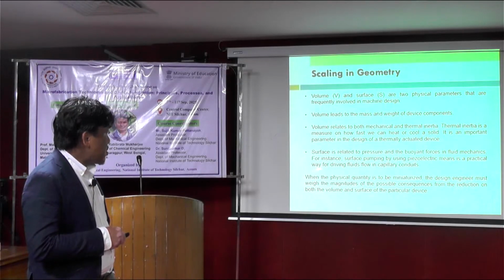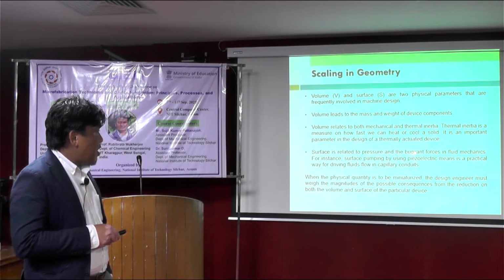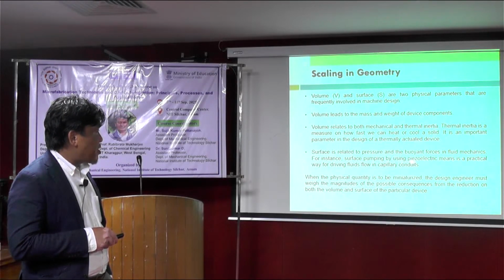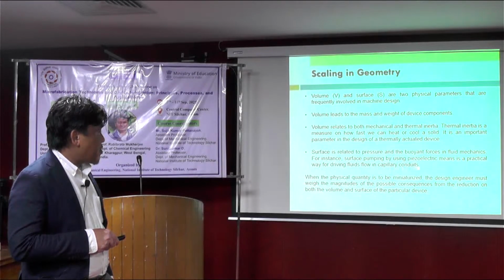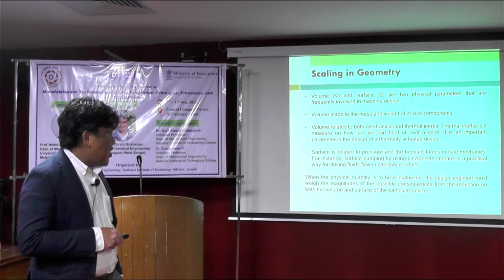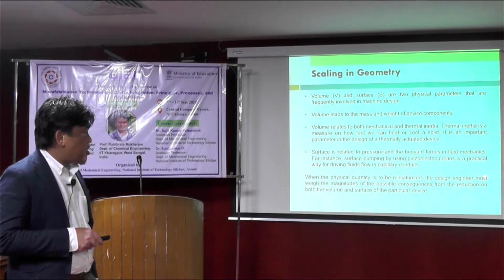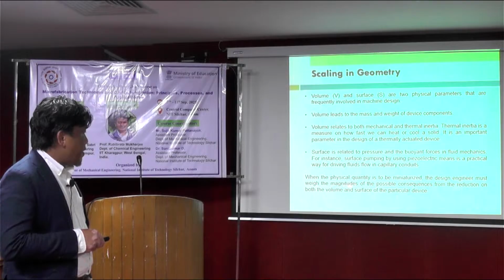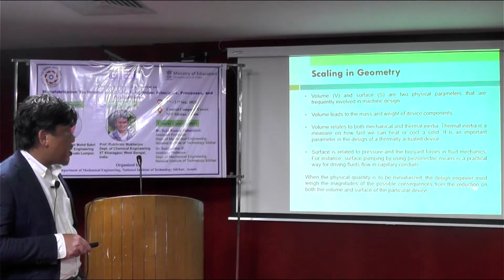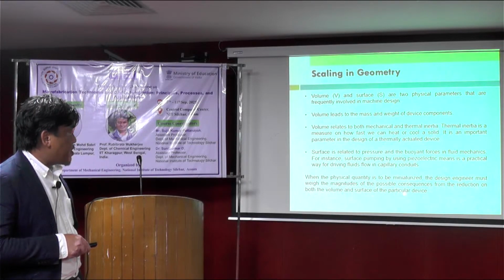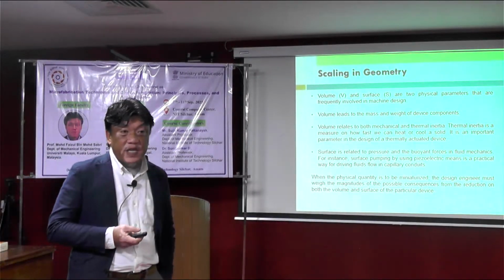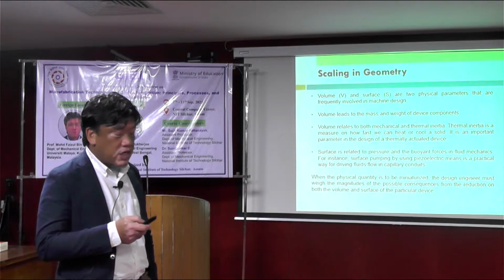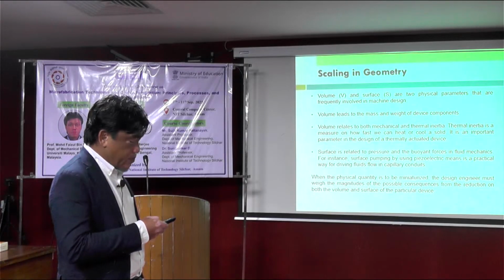And surface is related to pressure and buoyant forces in fluid mechanics. For instance, surface pumping by using piezoelectric means is a practical way of driving fluid flow in capillary conduits. When the physical quantity is to be miniaturized, the design engineer must weigh the magnitudes of the possible consequences from the reduction in both the volume and the surface of the particular device. So it's all about the volume and surface ratio, basically, if you look into the device at the micro scale, the behavior.